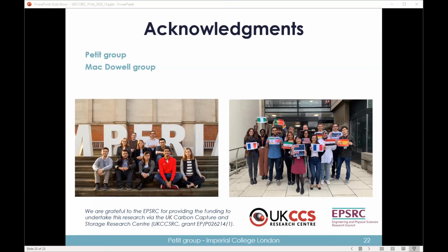It was kind of a question, you've just touched on it, about isotherm measurements. So you gave some tips to experimentalists about recording at least 3 at different temperatures, et cetera. One thing that you didn't mention that I've come across quite a lot is the effect of pre-treatment. So all the data that you're getting from the literature is excellent regeneration, right? Yeah, exactly. Do they pre-treat in the same way for the same amount of time, using a vacuum, same temperature, because it totally changes the properties of the sorbent, right?